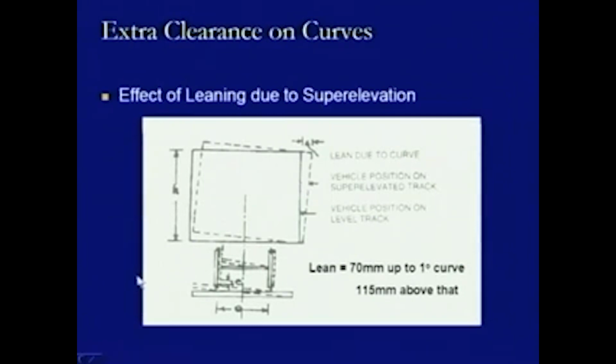As soon as we come to a curved section, the super elevation will be there, and because we have taken this as an outer side and this as an inner side, this outer side will be raised, say by a value E at this level, and this is how the inclined surface is formed. This is the inclined surface which defines the provision of super elevation. Now, when this wagon is negotiating this super elevation, this will go up and this will remain in its normal natural condition. So, this is going up in the level.